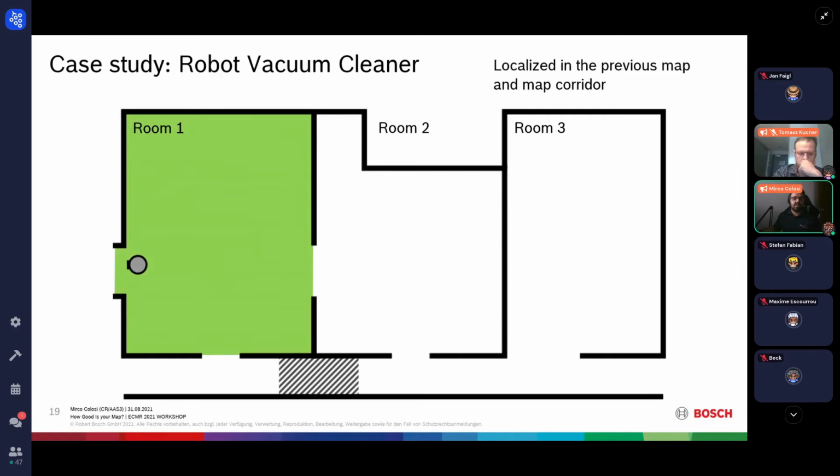of the unknown environment. The planner now decides that it wants to go toward the corridor, and the robot turns on the spot, understanding that it's an already known environment, so it avoids mapping it again, and just localizes in the previous map. Once the robot reaches the corridor, it enters and creates a new map for the area.